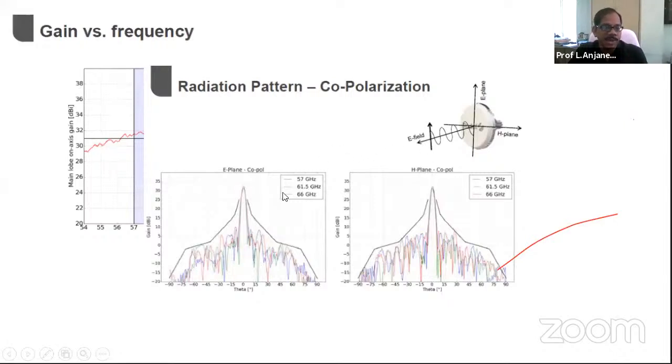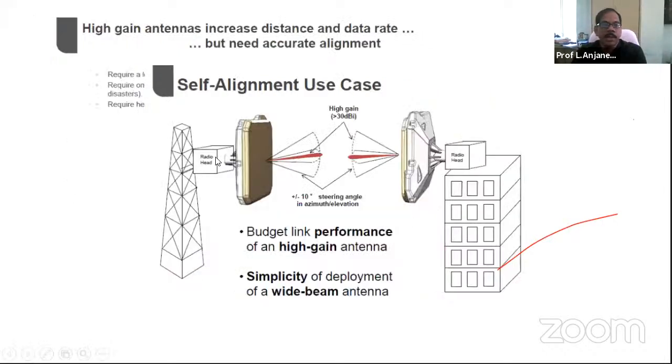All these are millimeter wave antennas for long haul backhaul. Here are some of the radiation patterns of the antenna. You see the beam is very, very sharp. It's a pencil beam actually. So the pencil beam has to be aligned between the transmitter and receiver. Then only they can receive. Now let us say self-alignment. They use a self-alignment technique so that the beams are perfectly aligned.